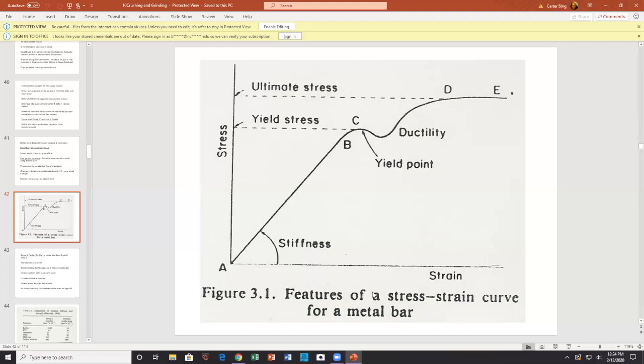All right. All you got to do is hit it with a force and see how much it strains, and then figure out what the yield stress is. And these are not some theoretical things. These are things you can actually measure if you spend a little bit of time at it. Okay. You do not, principle of engineering is you don't have to accept what's available. You can make changes to improve your processing.